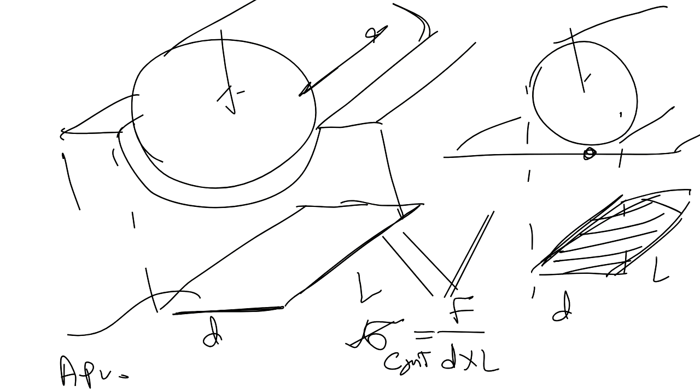Yani, for example, in a case like this, let's assume that this is our cross section and this is our neutral axis. Maybe I'm looking for the stress at some point here for some reason. So your y in this case will be that distance. You got it? So we have y1, y2, y3. But if you say y, absolute y without any subscript, it means the maximum y, which is the y at the upper or lower layer. You got this one, guys?